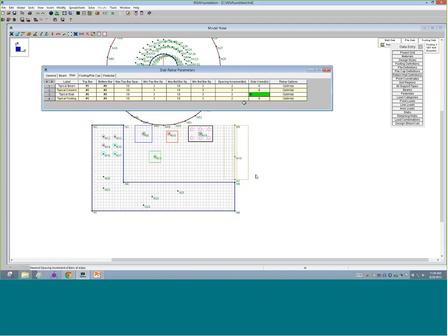Side cover. At the side of each strip, we know about top cover and bottom cover, but at the side of each strip, if we want to have a little bit of a gap so we don't just lay your first piece of reinforcement out there, we might want to put a cover. But we leave this typically as 0, and we see what we need to do to fill in. But if there's a condition where you need to bump the side so you have no reinforcement on that side, you can do that. And now rebar options, and this is a question I had recently.